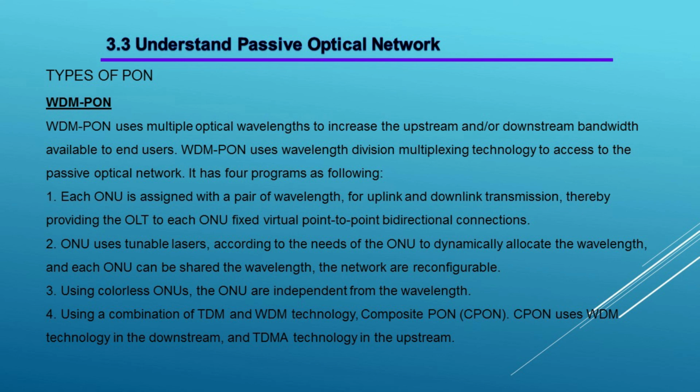The network is reconfigurable. 3. Using colorless ONUs, the ONUs are independent from the wavelength. 4. Using a combination of TDM and WDM technology, composite PON, CPON. CPON uses WDM technology in the downstream, and TDMA technology in the upstream.